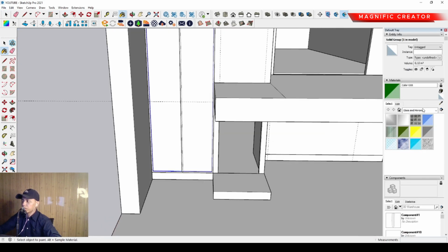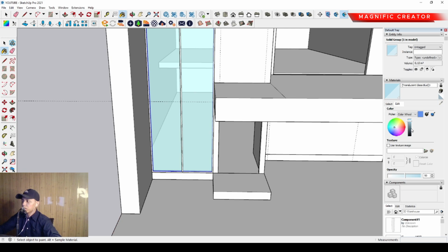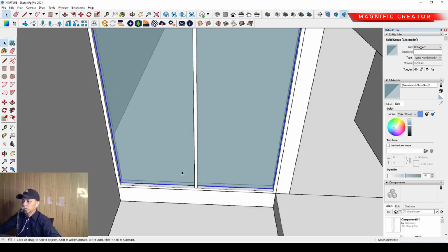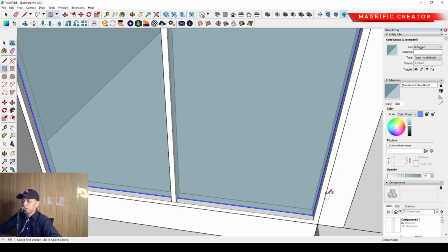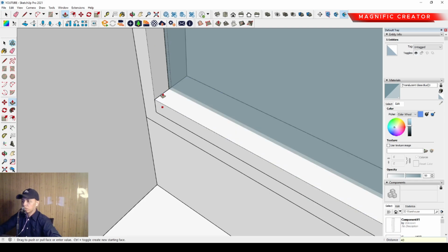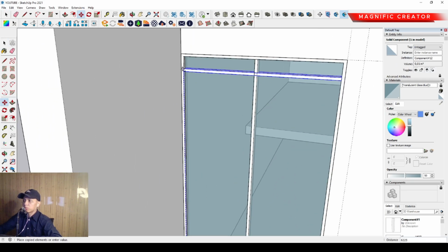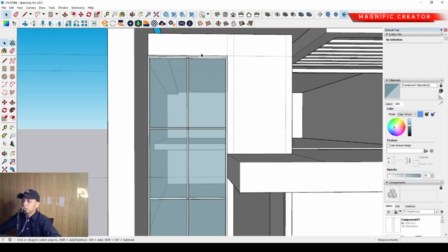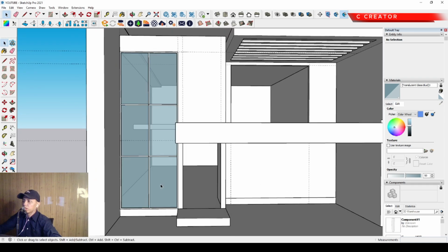Then we can make material. We can use the blue glass material temporarily, to make it easy for us to modify the window element. So then we can make another window element with a window frame, with a rectangle starting from here until this position. So then we can push it up around 40 millimeter. Then we can just make it a group and create a component. Then we can move and press Ctrl to duplicate it until this position. So then we can type 3/ and enter, so we get the automatic division of this window panel element over there.